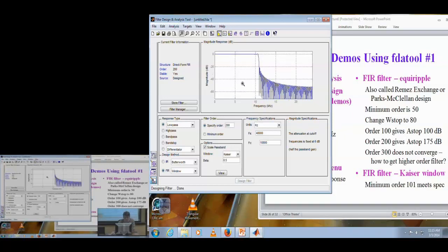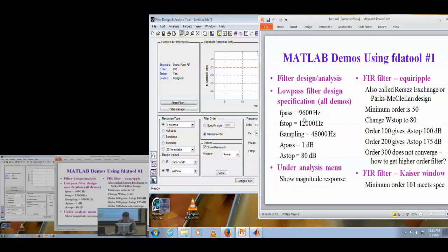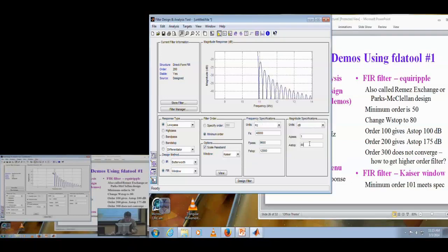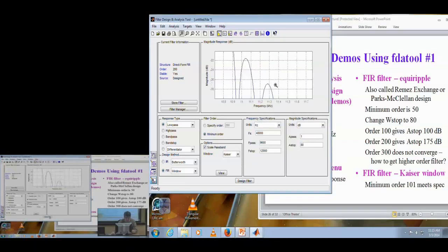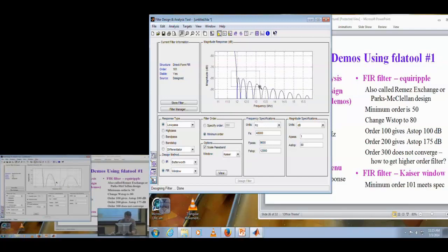Let's try a 200th order FIR filter. It's not really impressive. We can play with beta. We can play with some different things to get a better order. Or what else can we do? We go back to Kaiser. Is that cutoff frequency supposed to be the midpoint, and it wasn't? Well, it is a midpoint between passband and stop band. So if we're off by, let's go back to the design we had. How many dB are we off by? Not much.